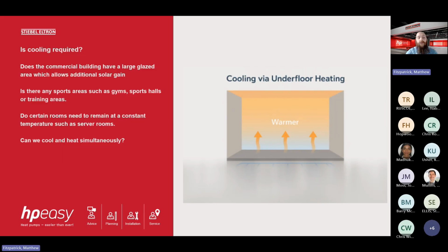However, when you compare it to an air source or ground source heat pump, to add air conditioning on to your existing renewable heating package, you've now got twice the component cost, twice the servicing cost, twice the maintenance and breakdown cost. You've also got 2 control systems, which if you're manually operating these, you will find there's a crossover where one person might want the room at 18 degrees and someone would like it at 21. So someone will switch the air conditioning on while someone switches the heating on. So you've now got a battle of the forces effectively taking place in this area.